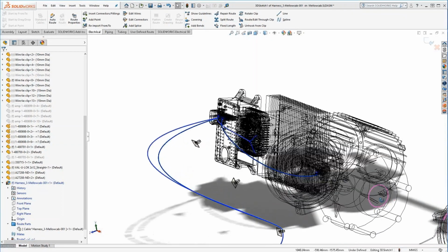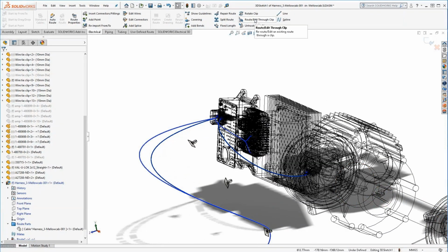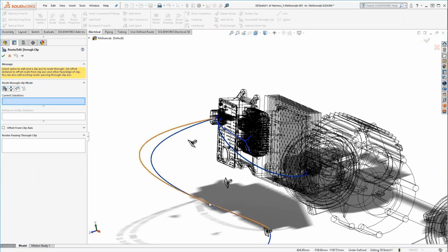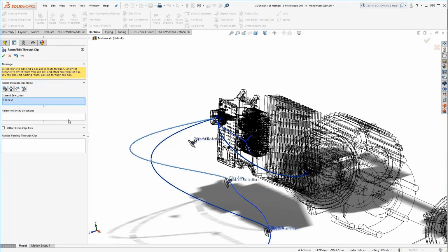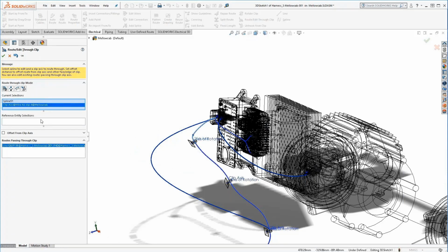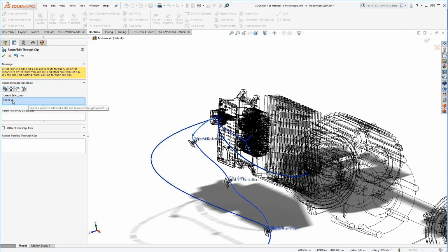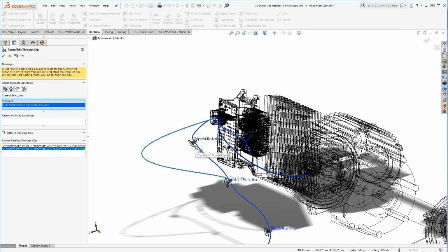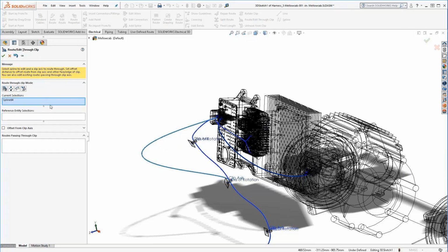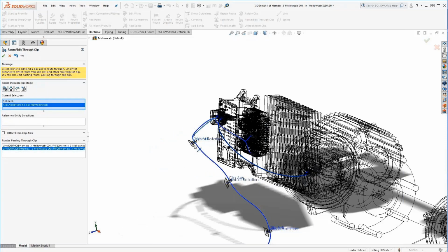And I'm going to again merge all these wires together. But you can see that the concept is that you need to create this Excel to define the point-to-point connections. Once it's loaded, SolidWorks knows exactly how to join these different pins. And the next step will be to edit this path to align with the geometry I'm using in my assembly. Okay, so that's what I'm doing here. Okay, just like this.